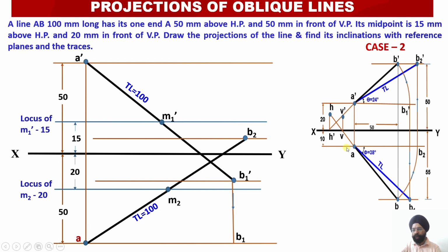Then what I need to do is keep my needle here and rotate it back to the second point of the true length of the plan. I will get my apparent length projection point B. So from here, again you see, I'll keep my needle here, open the compass this much, and now I will be rotating it to this locus line B2.